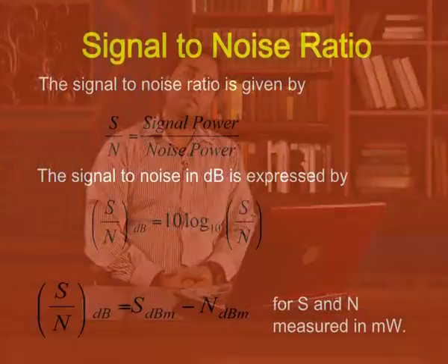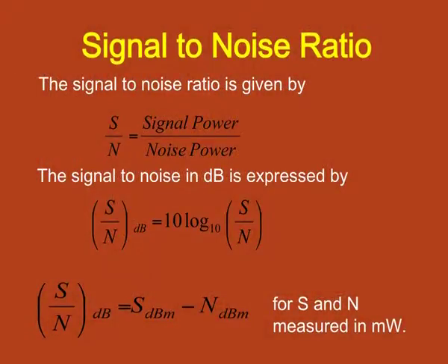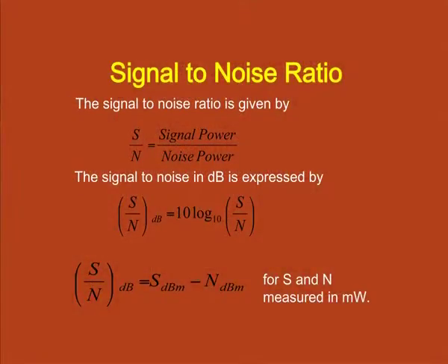Now, we will introduce the concept of signal to noise ratio. As we said, the concept of bandwidth is also related to signal to noise ratio. Signal to noise ratio is defined as the ratio of signal power to noise power. So, what are we interested in? We talked about thermal and shot noise having uniform spectral density. If we are interested in wider and wider signal frequency ranges, then what will happen? The signal energy is finite, whereas the noise energy would keep on increasing.